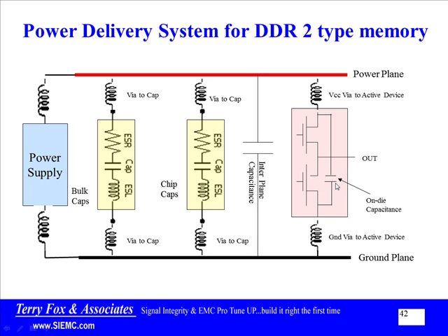Now, with the exception of the top end Xilinx Virtex and Altera Stratix, whatever it is, they don't tell you what this inductance is. Now, if I don't know what the on-die capacitance is, I don't know how high in frequency I need to have a low impedance as far as these planes are concerned. So we get sort of into a catch-22. If you gave me infinite on-die capacitance, I wouldn't need any of this stuff. All I'd need is just the power supply. Give me a battery and some long wires, and if I've got enough capacitance here, then everything's fine.